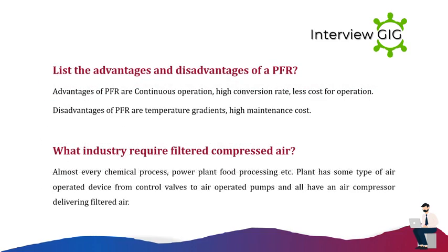List the advantages and disadvantages of a PFR. Advantages of PFR are continuous operation, high conversion rate, less cost for operation. Disadvantages of PFR are temperature gradients, high maintenance cost.